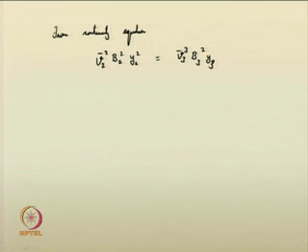So, from continuity equation, and in the next class we will derive the relationship of a particular parameter for the obstruction. So, from continuity equation I can just suggest now by squaring the terms, V2 squared y2 squared is equal to V3 squared y3 squared, like this, right. So, just incorporate the Froude number and we will get a particular relationship.